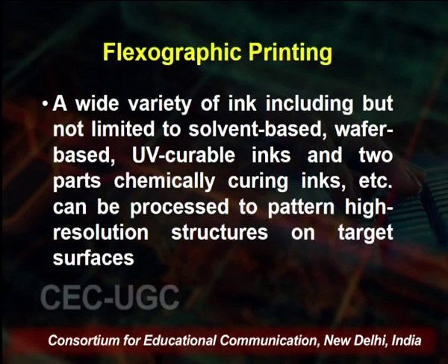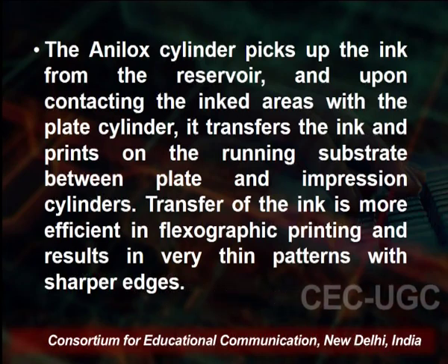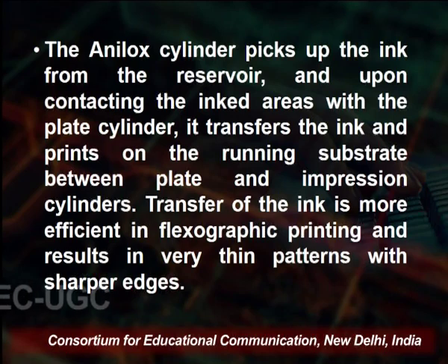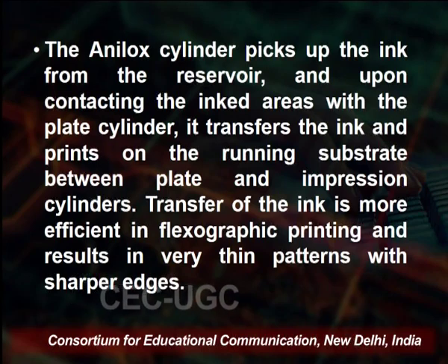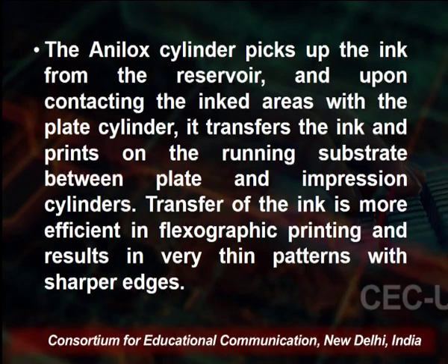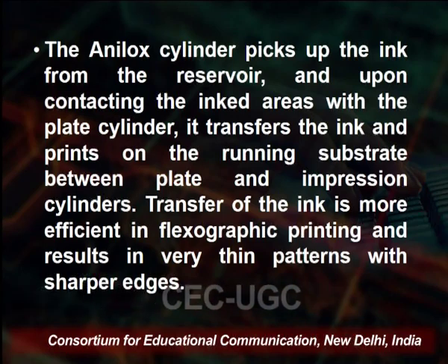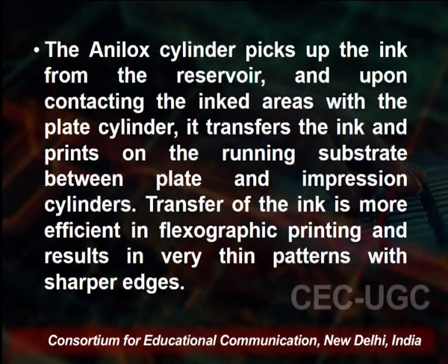So we use a cylinder, that is the anilox cylinder, picks up the ink from the reservoir, and upon contacting the ink areas with the plate cylinder, it transfers the ink and prints on the running substrate between the plate and the impression cylinder.